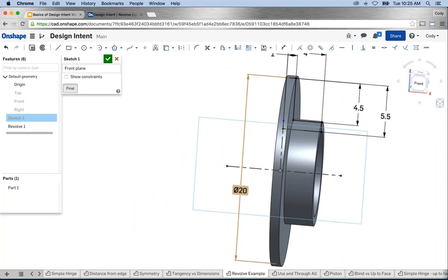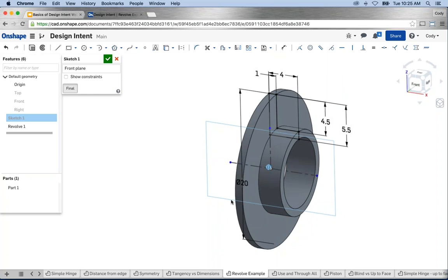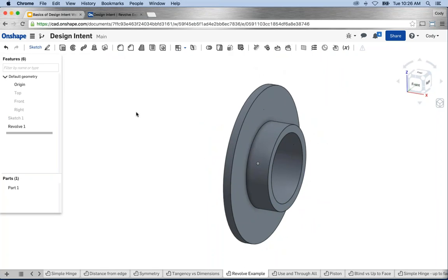And so now I've taken, building my simple flange, for example, from 3 different dimension changes down to 1 when I want to build a new version. So it's all about how you handle your dimensions and how your sketch is constructed. And this is a very simple example, of course, but there's lots of things you can do to build design intent into the way you've laid out your dimensions or your relations. Okay, so simple example with a revolve. The important thing I want to point out there, how I construct my dimensions makes a big difference.